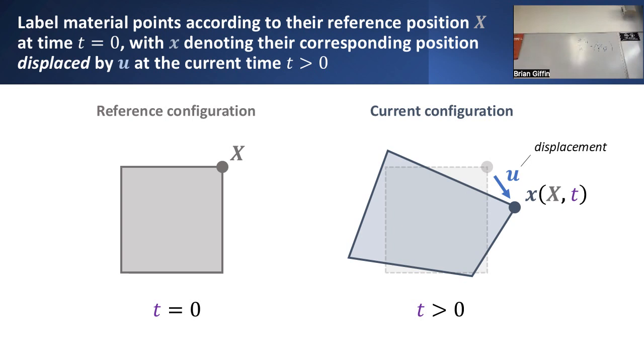I can look at particular material points in this cube, let's say this corner, and I can give it a name that corresponds to its spatial coordinates. In fact, I will call points whose coordinates are specified relative to this reference configuration of this body capital X. So canonically, if I'm denoting things in this lightish gray color or using capital letters, I mean reference configuration coordinates describing points in this originally cubic domain.